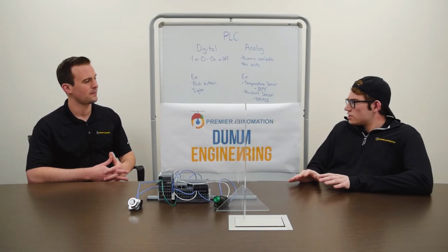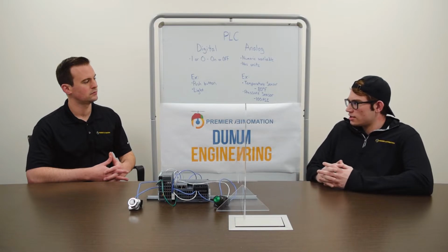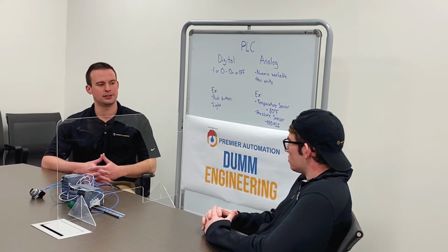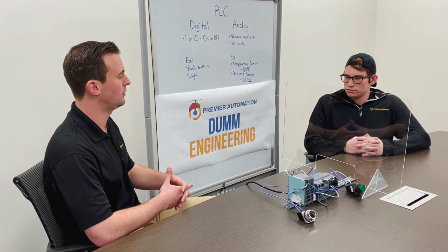We're not going to cover this today, but with communications, do these generally have other forms of communications, like other protocols that they can talk with field devices, or such as a drive, to transmit information? Yes, typically PLCs can also communicate via the ports that they have on them. A standard port that a PLC has is an Ethernet port. Basically, it sends packets of data to and from a device that it wants to communicate with all over one wire, instead of having many, many different individual signal wires.